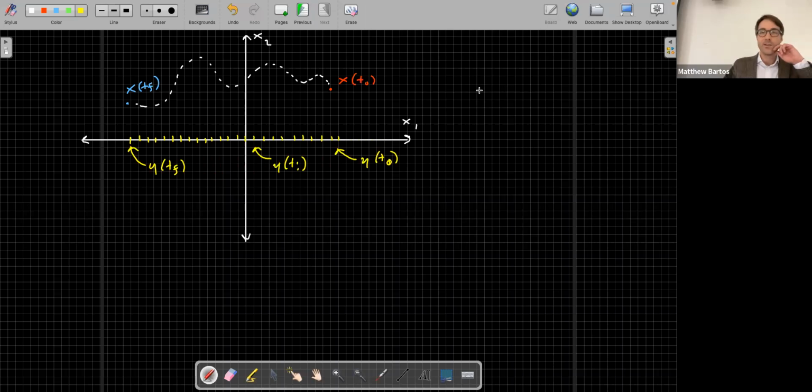Okay. So just as before, we can take a look at the system in discrete time step by step. And we know that our observed output yk, let's just assume that there's no input to the system. So it's sufficient to just look at the case where there's no input. So we're going to assume no input u. In other words, x at time k plus 1 is just equal to A xk. And yk is going to just be equal to C times xk.